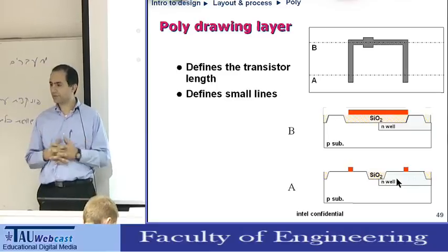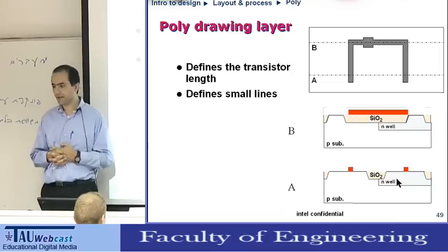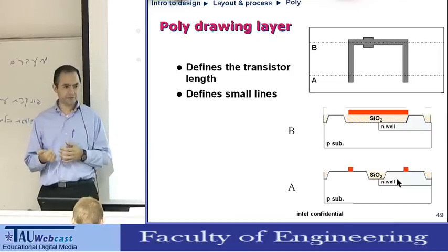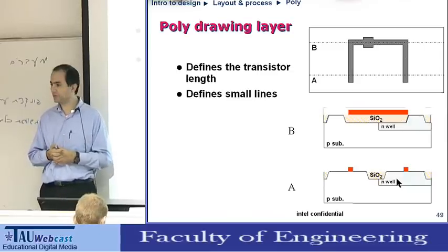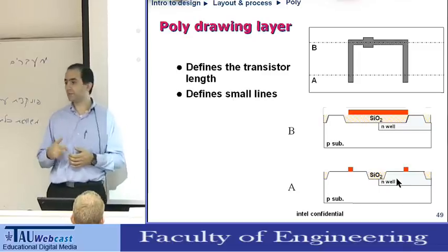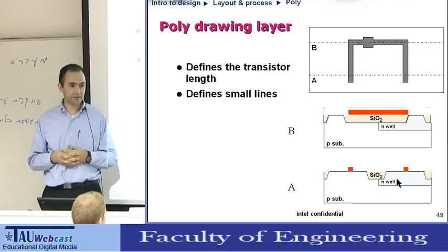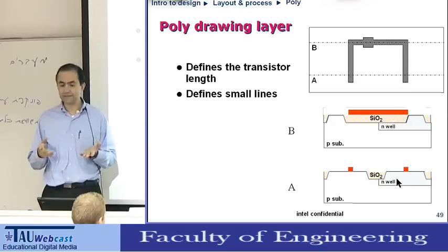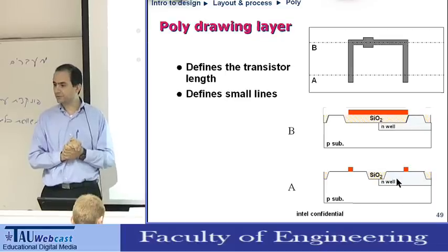What will we do then? How will we know when to stop? So either with timed etch or with endpoint. Endpoint is obviously better. And then what will we do? An over etch, potentially even more selective, because we want to harm less the oxide, which is the stopping layer, and it's usually a very thin layer. Okay. And then after we do that, what will we do?